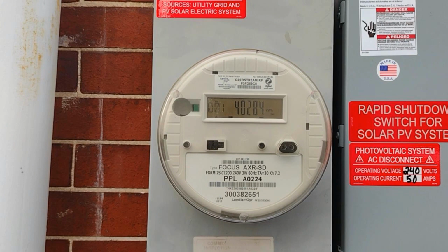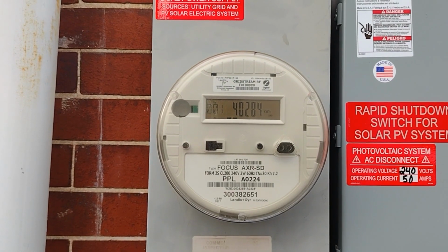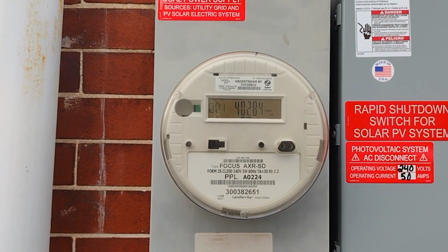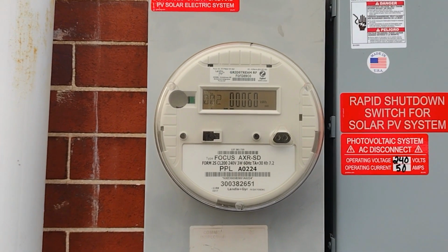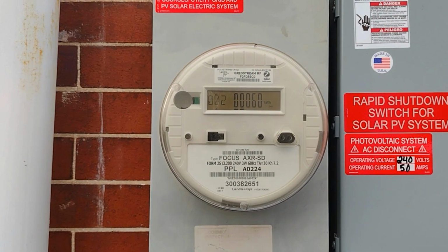That's the lifetime kilowatt hour counter. That's kind of like an odometer in a car. It always goes up, it never goes down. Whether you have a backfeed system or not, it still always goes forward. If you're backfeeding, it just stops going forward. The second, number 2, is your backfeed counter. If you have some kind of solar generator, this is how much power you're feeding back into the system above what you're using for yourself. This is also like an odometer. It always reads forward, it never reads backwards.